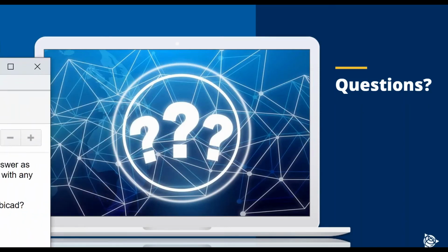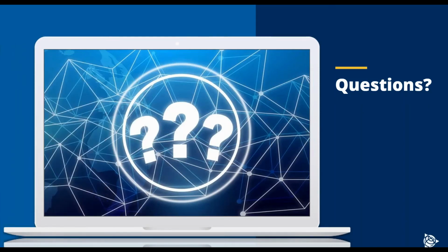It's quite easy. Probably we'll work together with you because we need to make a small change. You need to add a code in front of your view template, which is S4R underscore, and then the function will recognize that view template as well. So once you do that, when you launch the function, you'll be able to see your view template, and you'll be able to create both ceiling plans and floor plans with your view template.